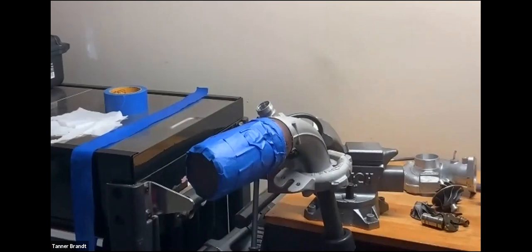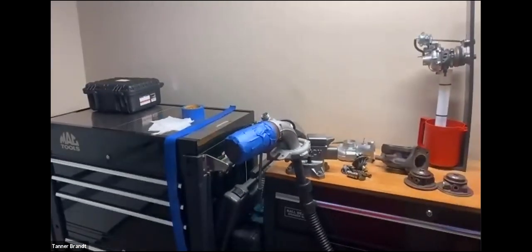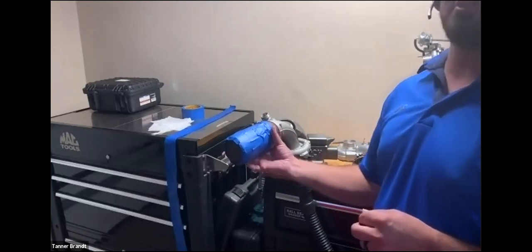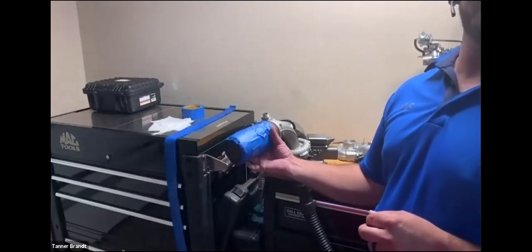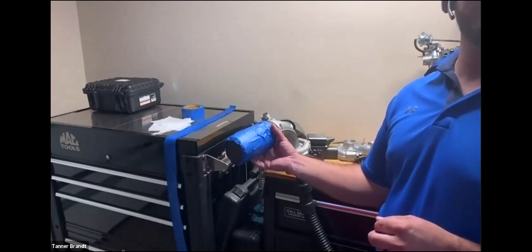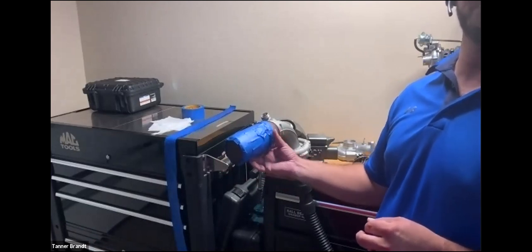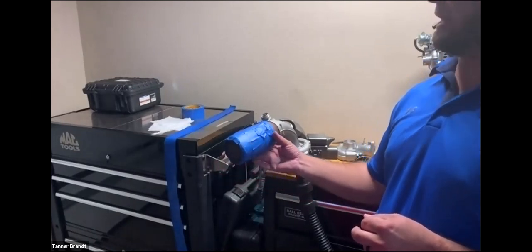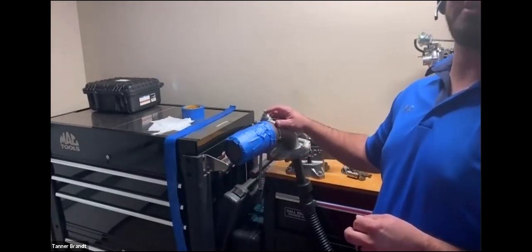So does that make sense to everybody, what we just did and why? Yes. Okay, cool. That's a nice, easy experiment. So all we're doing with the tape is because obviously I can't in real time make a turbo or an air filter get dirty in real time. So it's no different though. As you tape off an air filter and it starts to get clogged, we're going to start putting vacuum here.